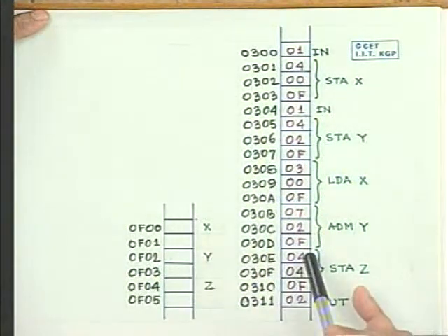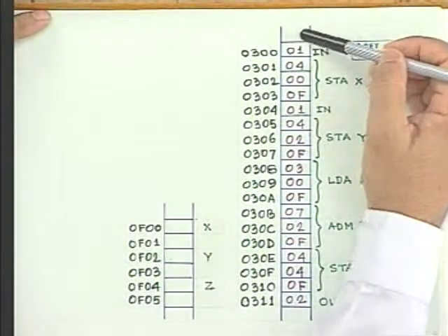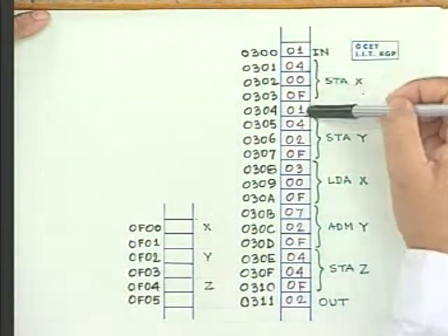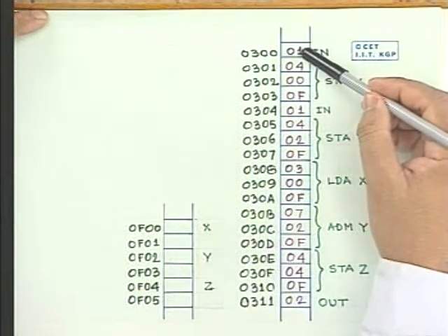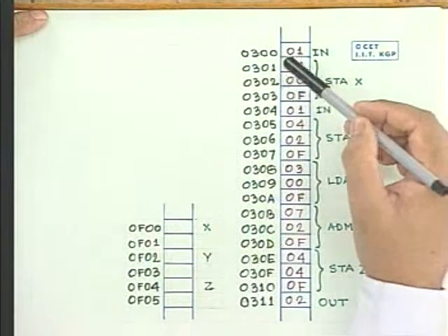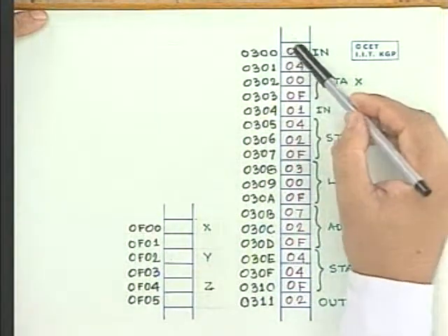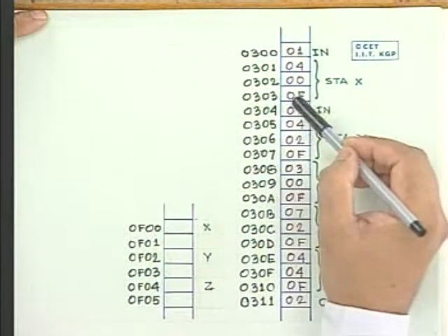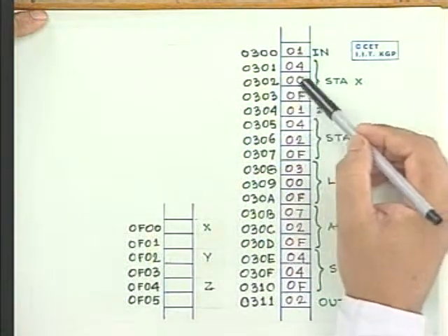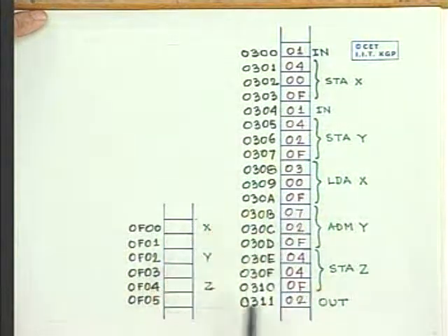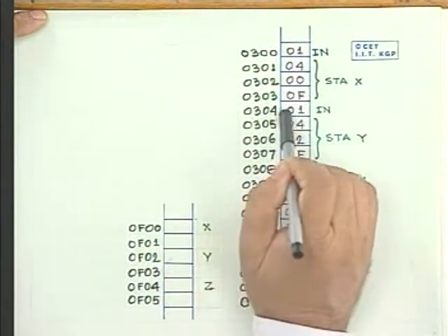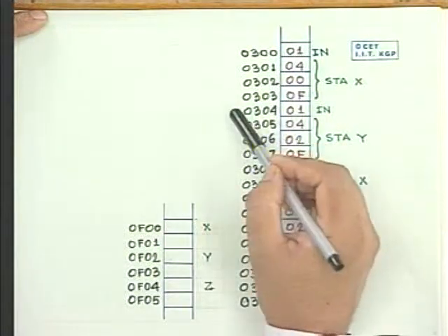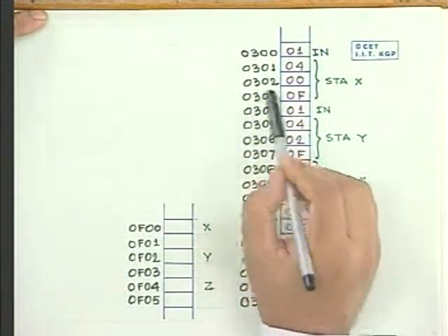Therefore, I am talking in terms of a memory which is byte oriented, in the sense every byte is addressable, but if we want, we can take out or push in either 1 byte or 1 word consisting of 2 consecutive bytes. That is the assumption I mean whenever I'm talking about accessing the memory to take something out of it and to write something into it.